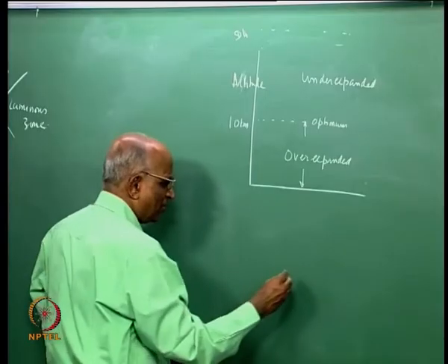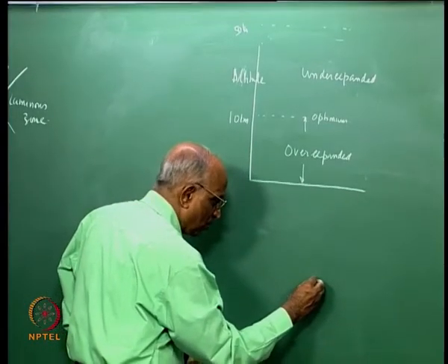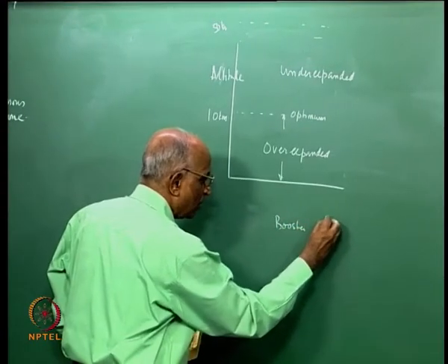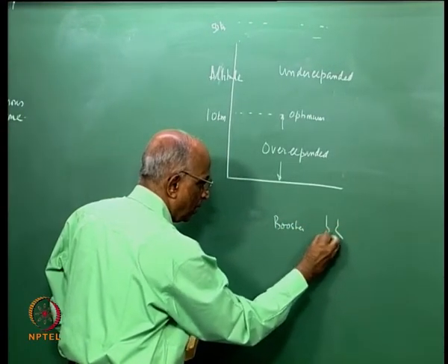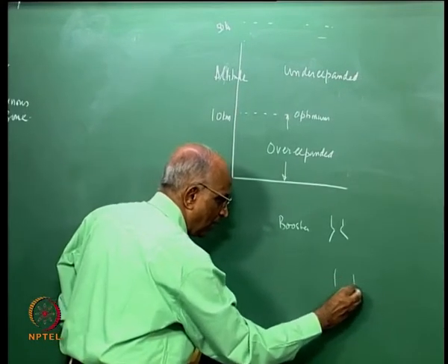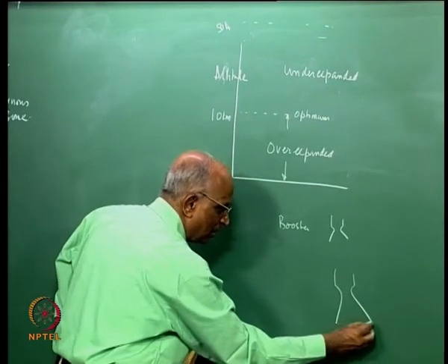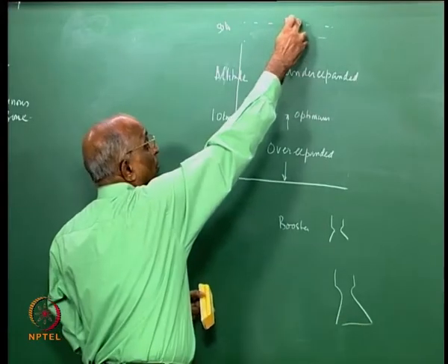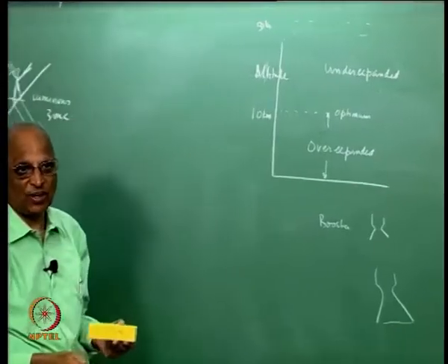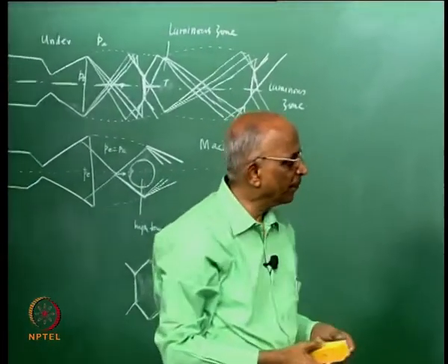As you would have seen in the earlier figures, a booster stage has a small nozzle, whereas if the rocket is going to fire at high altitude, I will design it with a larger nozzle such that the optimum shifts to the higher altitude, and this is something which we have to keep in mind.